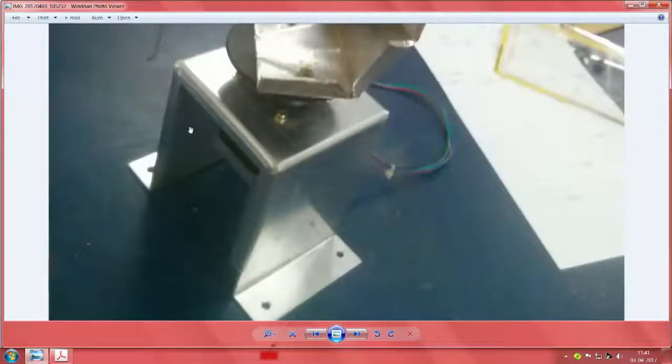Part of it in the real piece, what you see here on the corners, there is a small step, this is the one we saw here, and this small step is intended because of the sheet metal machine that we have there. We have a folding machine which has clamping fingers, and then the bottom jaw part of it, there is a limitation about the depth with which we can go. Hence, this cutout was necessitated when we tried it last time.